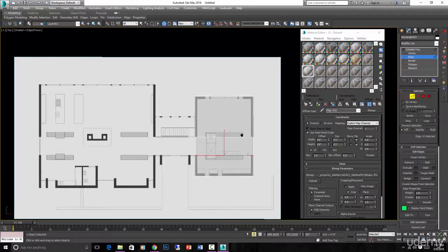So that works. The best way is probably hitting Control-Shift-A, which just automatically makes a slice straight through the edges that you hover over. So you can see as you hover closer to this edge over here, you can cut it there if you wanted. And if you drag along here, you can cut it anywhere along there. So that's a great tool, Control-Shift-A, which basically just puts what we call a loop straight into your model. So that's the easiest way to do that.